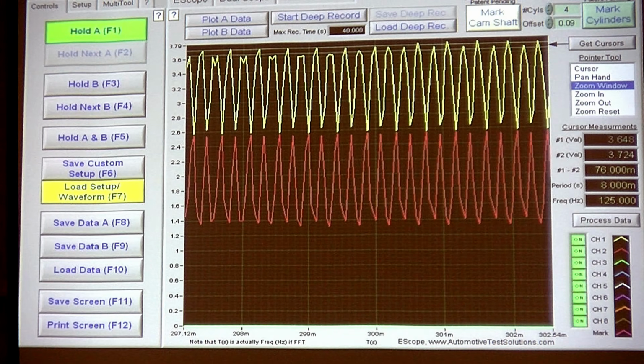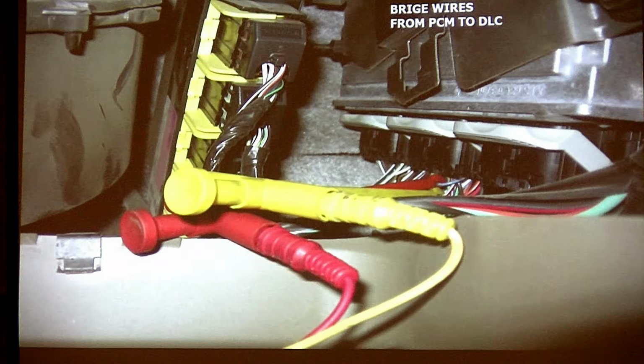The wires are broken. So between where I am and somewhere else, I've got more than one module, and I've lost my termination resistance. That's what's happened here. As soon as I saw this, I knew right away what's wrong. So the bus is ringing on this guy.